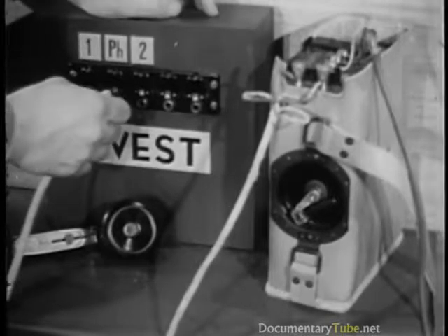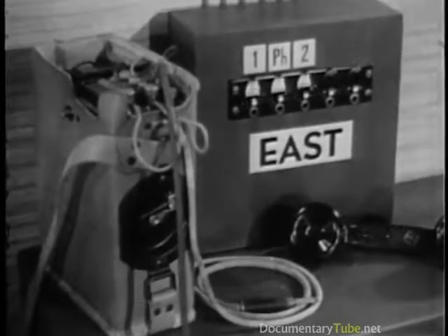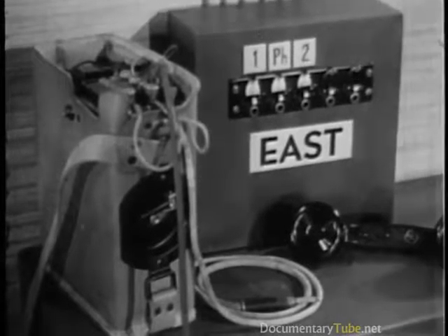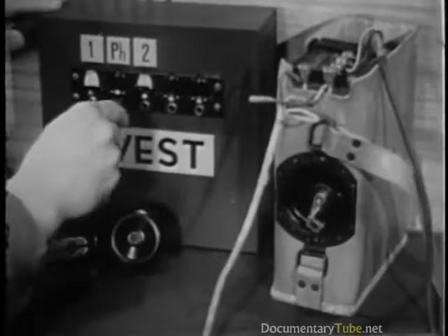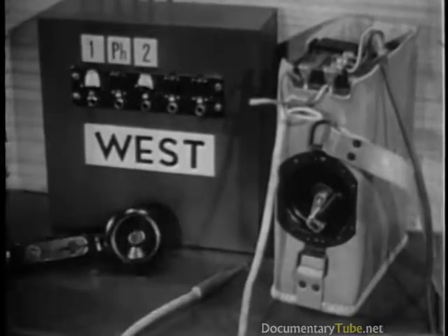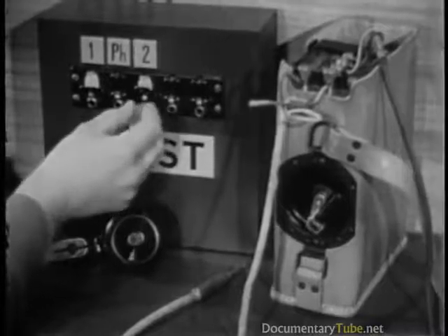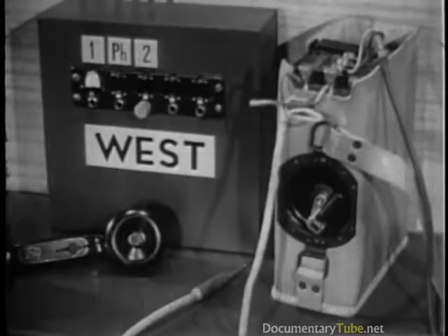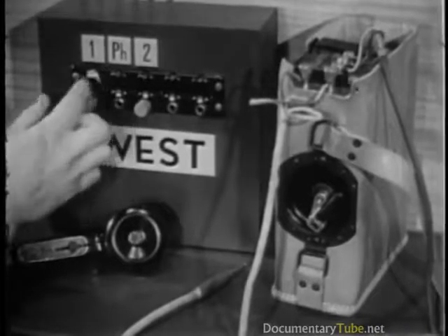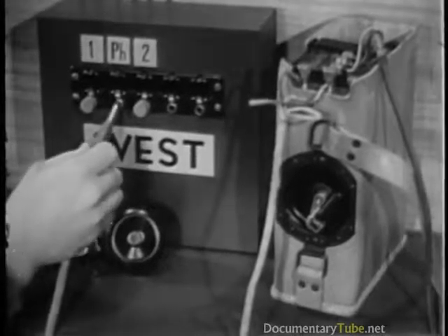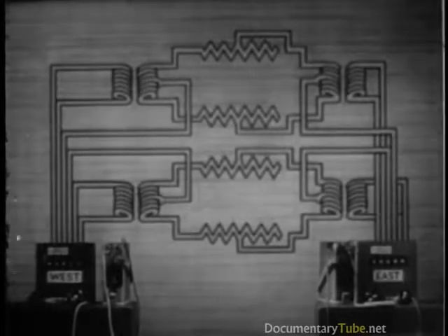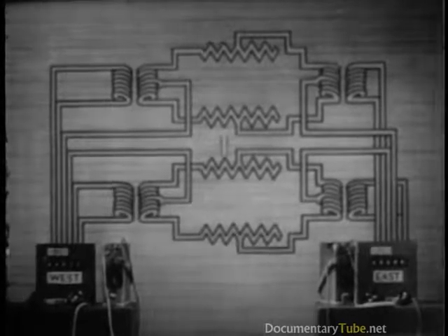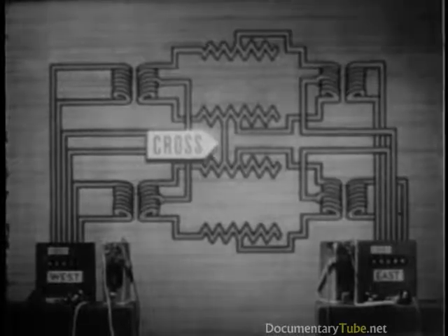We can still use one circuit by eliminating the other 2. The phantom is strongest, so we stop using the side circuits. They can't interfere with the phantom if we don't use them. Until the 2 open side circuits have been cleared, we can at least use the phantom. Here's a very common trouble which also affects all 3 channels: a cross between the 2 side circuits.